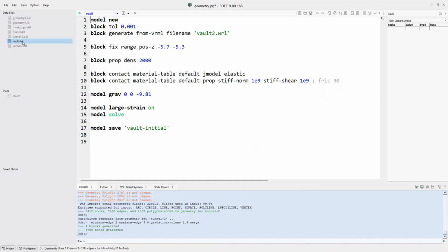The next one, this is something that people do if they're simulating masonry structures. People do this quite a lot with 3DEC. This is a slightly different approach here. We're not importing a DXF or an STL. It's a different format called VRML. The extension is often WRL. So you can create actual 3D shapes, 3D blocks in some CAD program, in this case, probably Rhino. As long as they're convex blocks, you can import them and then just automatically turn them into 3D blocks.